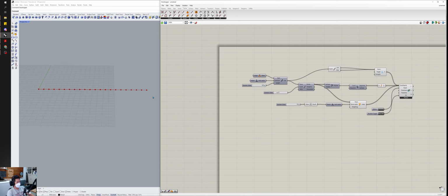Now, that's because we didn't define the physical characteristics of this line segment, right? So because we didn't define that, it assumed that that line segment was infinitely stretchable. It had no physical properties to it. All it was, was something that was connecting those 2 points together. So what we need to do is define the characteristics of that segment.